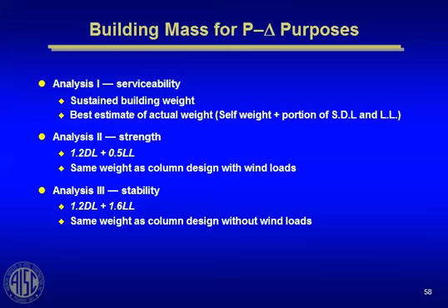Analysis 1, I mentioned we number our analysis 1, 2, and 3. Analysis 1 is serviceability. What mass do you use for these different load cases or these different analyses that we do? Well, you want to use the sustained building weight for serviceability and your best estimate of the actual self-weight of the building for that check.